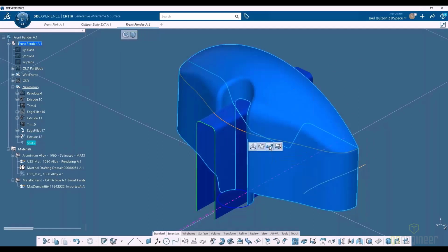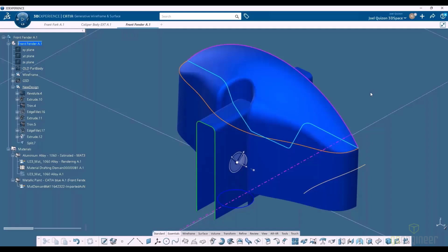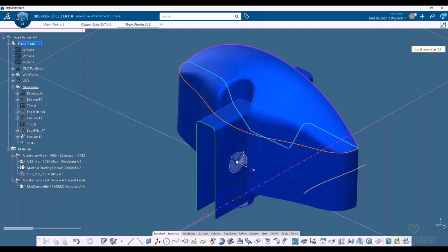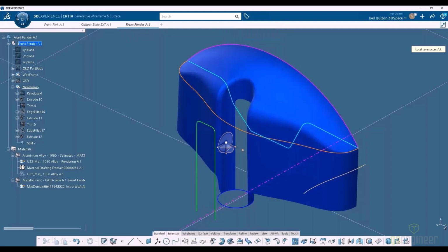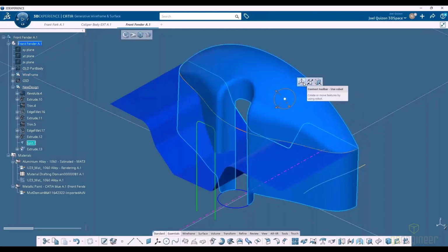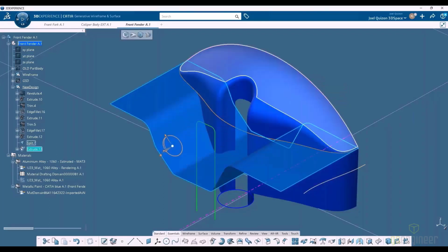This time I'm going to split the geometry. And the important thing there is I pick this one. The first entity you pick is what's going to get split. Going to go ahead and I could hide that surface. Let's just take this geometry here, and use this to split again.